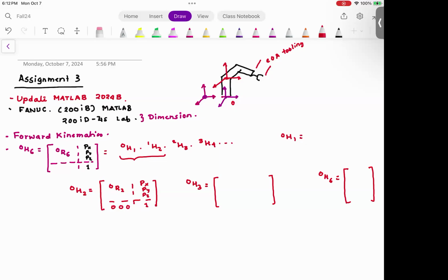The convention that we used in solving the forward kinematics and inverse kinematics uses rotation matrices. They don't use rotation matrices. They use quaternions. It's a whole different way of solving the problem. So you have to go step by step to make sure that your forward kinematics answer matches the physical robot end effector position. Only then you will get the correct answer. That is the reason why I asked you to do this exercise.